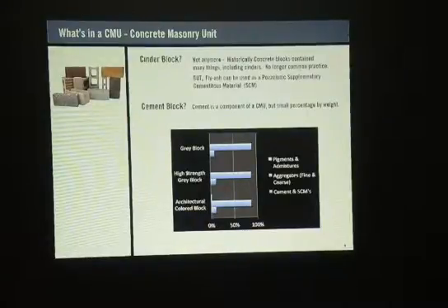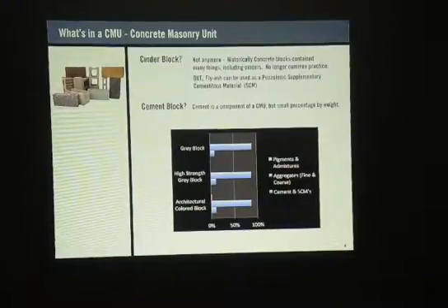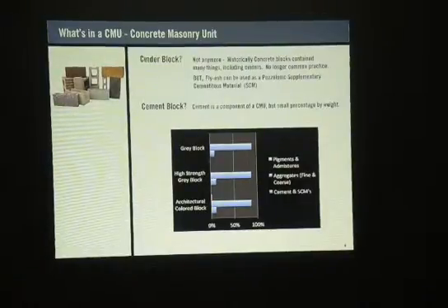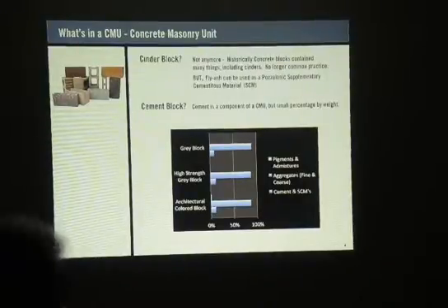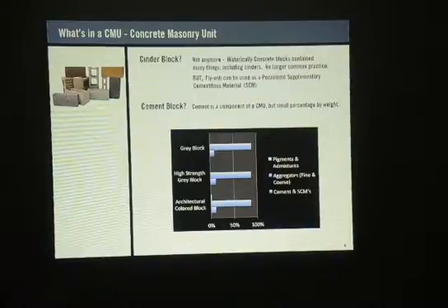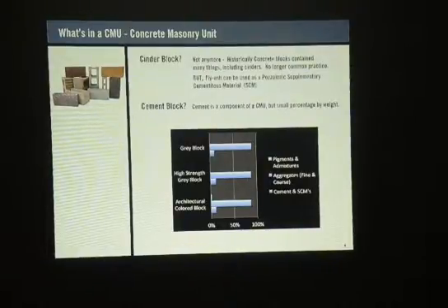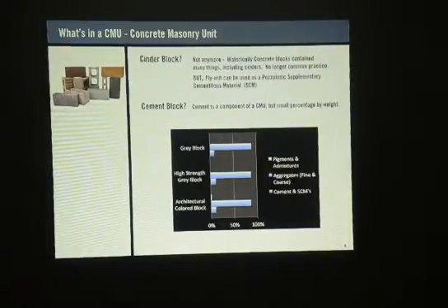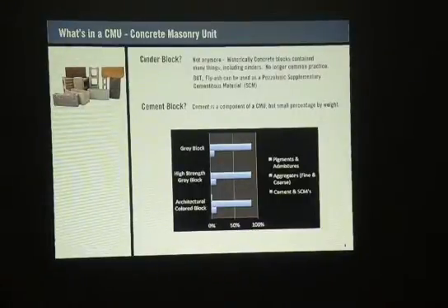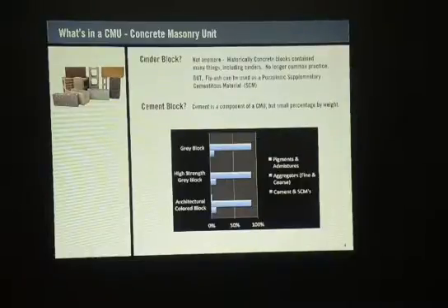And then we're going to start to see the surface over time start to deteriorate. And we've seen applications, I have over the years, because I've been doing this for 30 years now, where we actually have structural problems. And that's really sad to see, structural problems. It's because we didn't understand the encompassing needs of a building. So pre-insulated block prevents that. There's no condensation issues with pre-insulated block. That's the real benefit there.